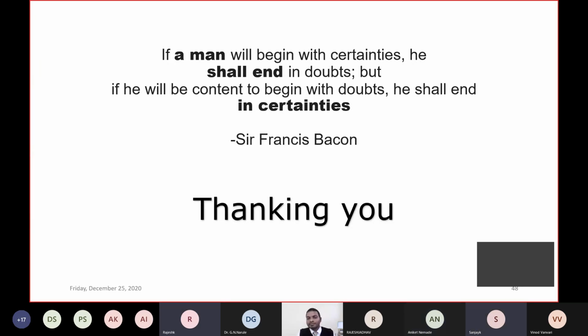I am Rajesh Kadare from D.Y. Patil School of Engineering. I want to ask you, have you come across a situation where you have been entrusted with the job of finding the SBC of a made-up ground? I ask because I was in a government department long back. There we came across situations where in very remote areas we were expected to construct a reservoir, an elevated service reservoir, with a staging height of about 12 to 15 meters. The land available with the Gram Panchayat is generally nearby, and it should be public land. So many times some made-up ground has been allotted to us. In that case, have you come across this, and what bearing capacity have you suggested?